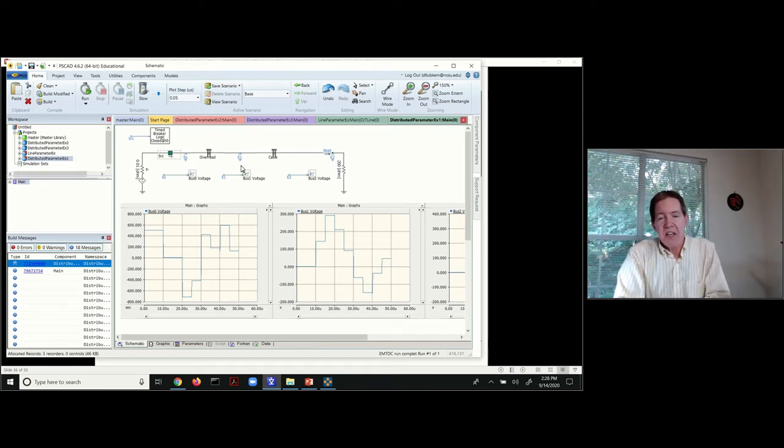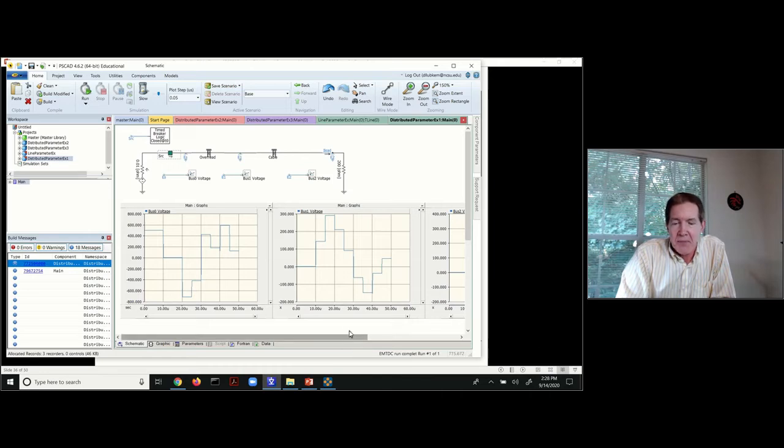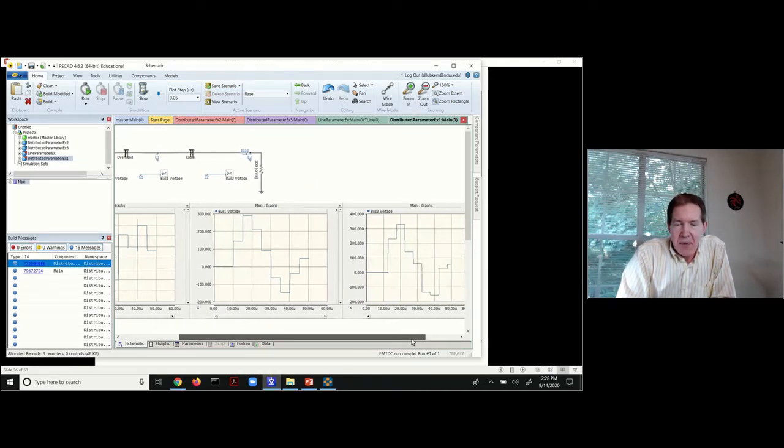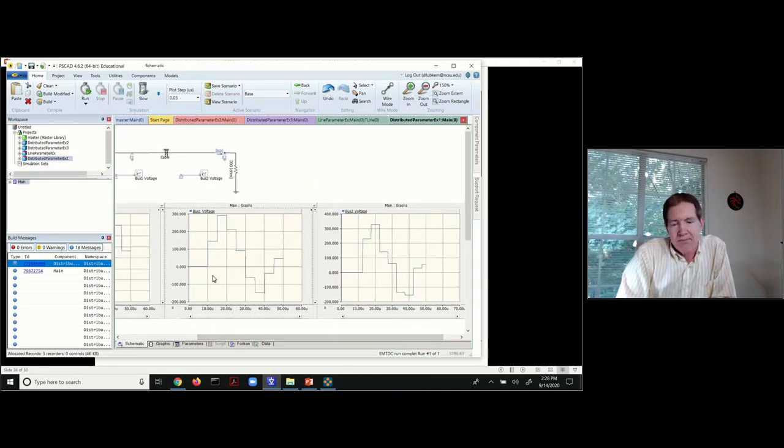And so you can kind of see them in the simulation, but what we're really more interested in looking at is what's going to be happening at the very beginning of the simulation, in the middle part, and also at the end. And what you could see in this case is at the end, we've got so much of that 500 kV that gets into the cable. That gets down to the load side, we've got the reflection coefficient.